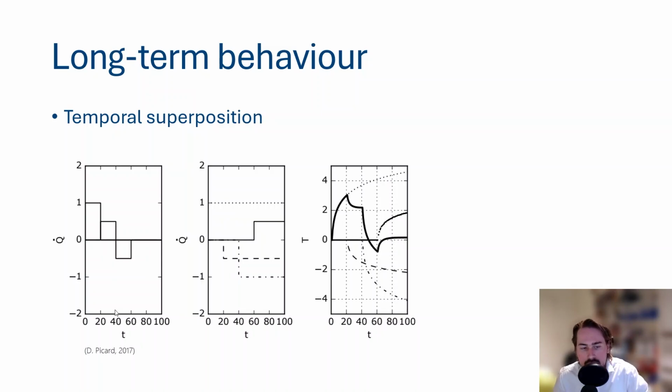Now the same later, so from 40 to 60 hours we have minus a half, and we come from a half. So what we do is we subtract another 1. So at time interval 40 we start another unit step, this time with a load of minus 1, so that together we have 1 minus 0.5 minus 1 together is this minus 0.5. And then again, going back to 0 means that we need to add 0.5 there. And that's the way we decompose our loads.